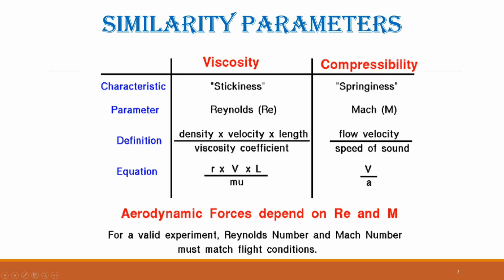Aerodynamic forces depend in a complicated way on air compressibility. At low speeds, typically below about 200 miles per hour, air can be treated as incompressible, meaning that its density remains essentially constant as the object moves through it. At higher speeds, however, a portion of the object's kinetic energy goes into compressing the air, changing its density. These density variations alter how pressure forces develop on the object's surface and therefore change the resulting lift and drag.